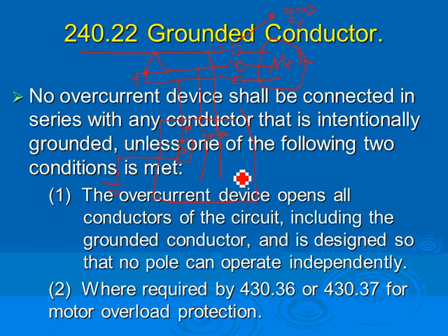And this is a single pole, single phase panel fed from a 3-phase system to feed a three-phase load. So if I have, say, a three-phase machine here, here are my two phases, and I grab the third phase and take it directly to the machine. So the third phase becomes the grounded conductor bar here. Anybody have seen this? You guys see this? Don't you ever design a system like this.